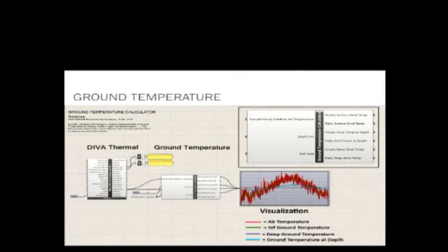And then we have soil conditions. So soil conditions actually determine at what depth the temperatures are stabilized. So below that temperature, we are pretty much seeing the same temperature profile. That's what you see at the purple line. And of course, until you go really deep enough, then you start tapping into the mantle temperatures. But we're not going to go that deep, theoretically speaking, at least practically speaking.